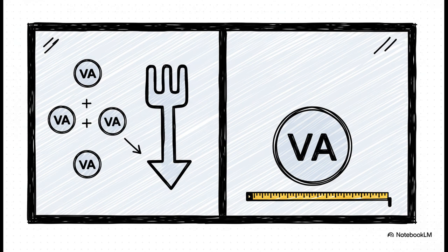When it comes to show windows, like in a retail store, the code actually gives you two different options. Option 1, you can calculate the load for each lighting outlet one by one. Or option 2, you can use a much simpler method. Just assign 200 VA for every linear foot of the window. The really important part is you have to pick one method and stick with it for that calculation.